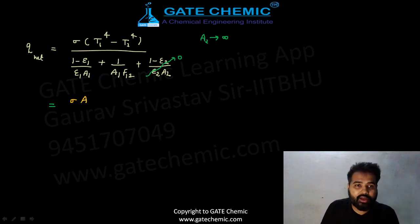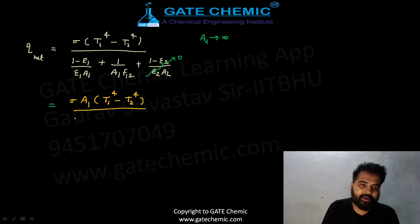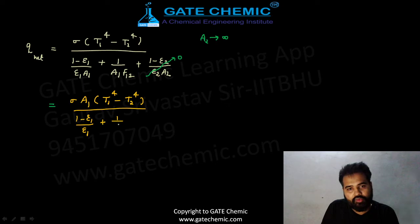So I can write the above equation as sigma A1 into T1 to the power 4 minus T2 to the power 4, and whole divided by, beta, 1 minus epsilon 1 upon epsilon 1 plus 1 upon F12. Now just put all values, beta, you will get your final answer.